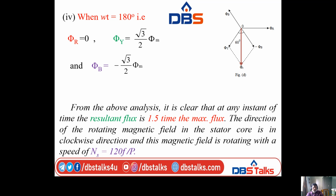Phi y, a positive value, you have to draw on one side, so this is phi y. Phi b is minus root 3 by 2 phi m, which is exactly opposite to phi y. Now the vector sum of these two, that is phi y and minus phi b, is nothing but phi r, that is also 3 by 2 phi m.